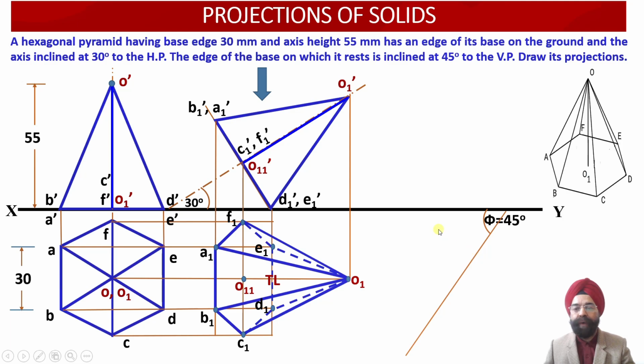We are going to draw this rectangular construction over here, and all the 7 points corresponding to the base, including the axis, will be appropriately marked within this rectangular construction which inscribes this hexagonal base. Thereafter we are going to mark the apex point using the rectilinear distances transfer. This way, the plan projection view which we had obtained earlier will be transferred or rotated at an angle of 45 degree with respect to the vertical plane.